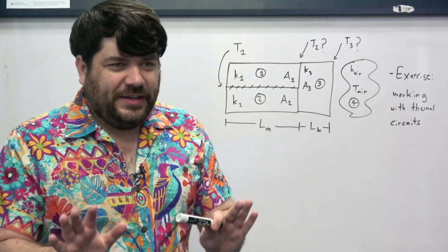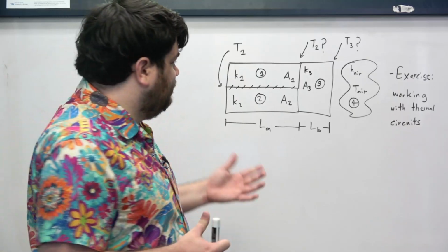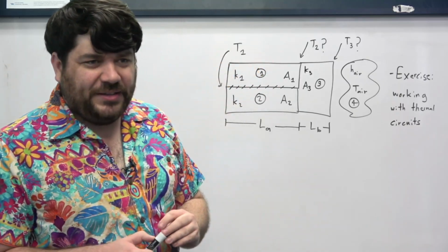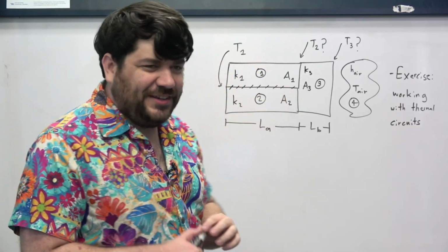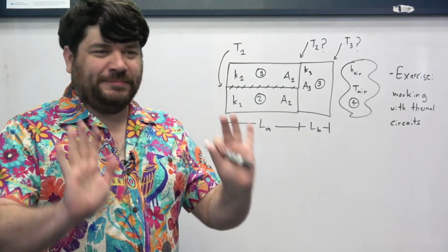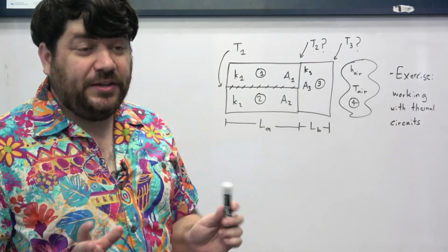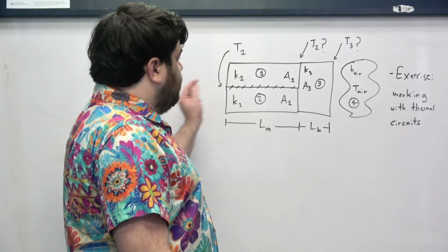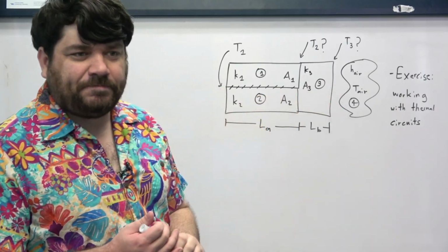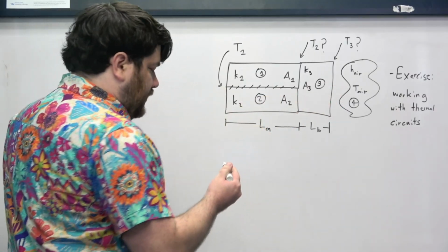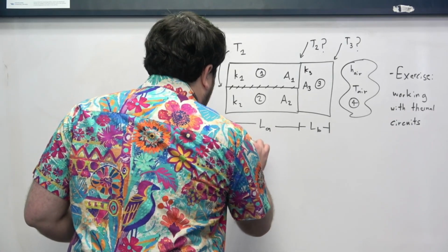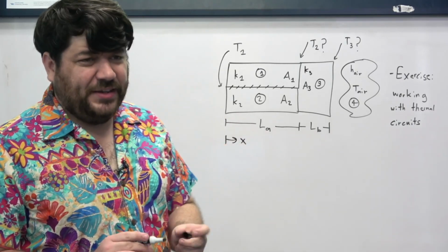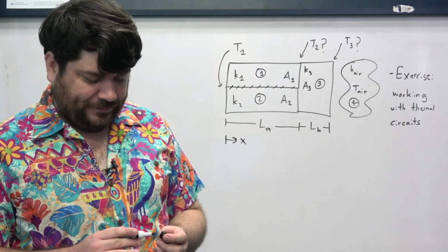And so if that is the case, we wouldn't be able to make the assumption, so we have to rely on the insulating strip and say, okay, heat transfer is only happening in one dimension, which is left to right or right to left. Okay, so we define a little x direction over here, and then we just say that heat transfer is only happening in the x direction.